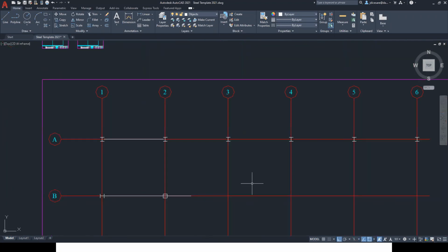Hold on a second. LTSCALE, LT scale. That didn't work. That's better. Okay, the LT scale was slightly off. 4,000. That's good. Okay, so guys, keep that in mind.